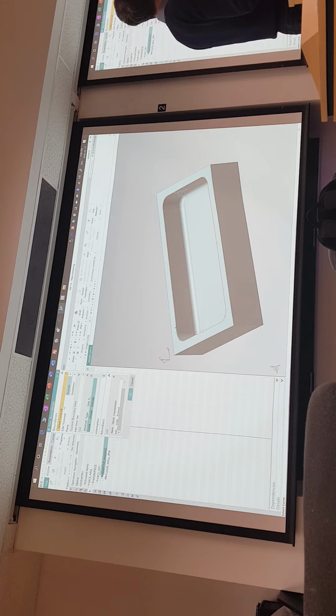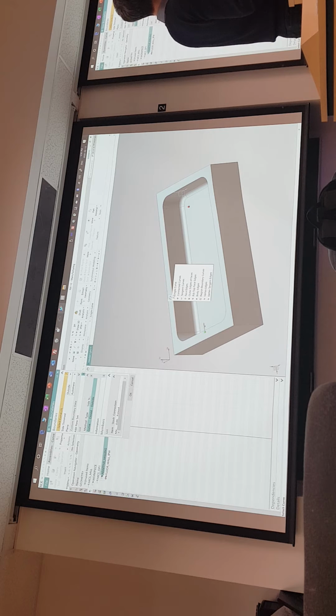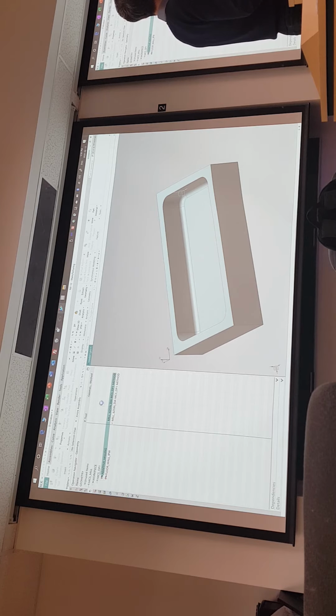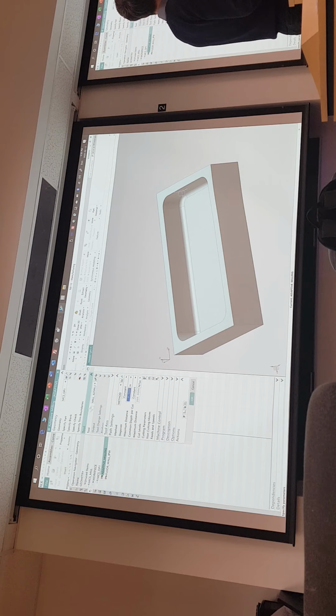And then when you select the curve, a nice trick when you select the bounding curve or the trim boundary. In this case, we want a curve, and then you pick an edge, and then instead of picking each individual edge along a part or a part with multiple pockets, you can just say tangent curves, and it'll pick all the edges that are tangent with that first one. Okay, so we've done the geometry.